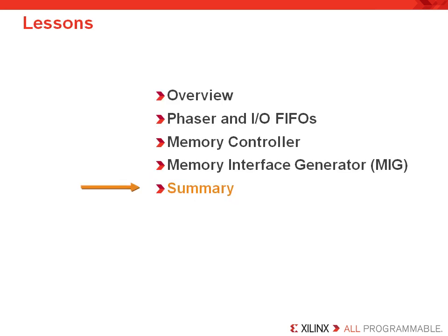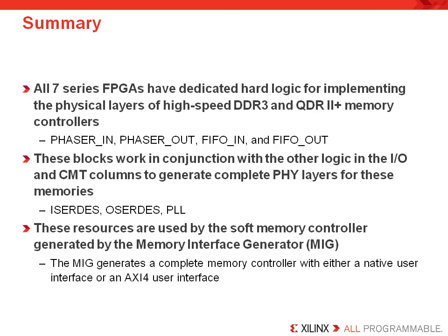Now let's wrap up this recording with a short summary. In summary, all 7 series FPGAs have dedicated hard logic resources for implementing the physical layers of your high-speed DDR3 and QDR2+ memory controllers. This includes the PHASER_IN, the PHASER_OUT, the IN_FIFO, and the OUT_FIFO dedicated hardware resources that are part of each I/O pin.